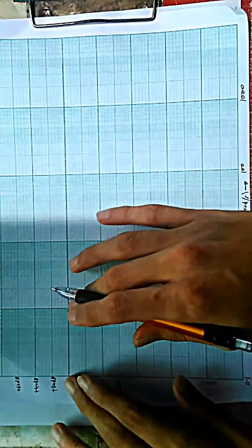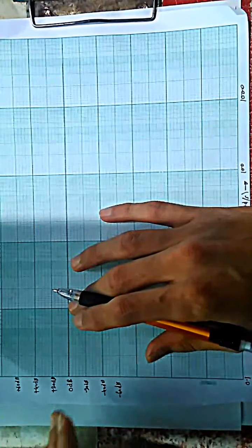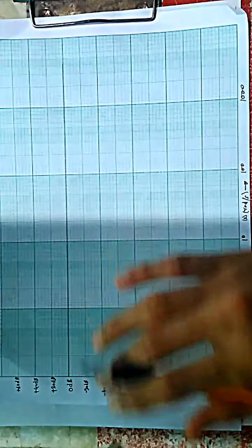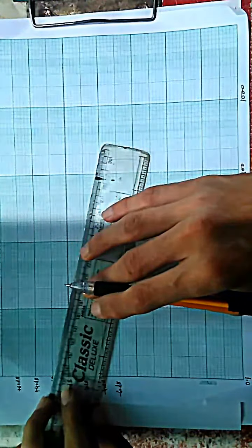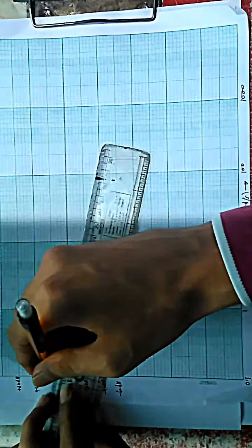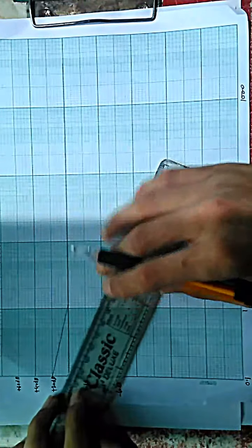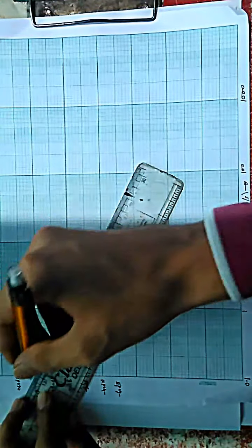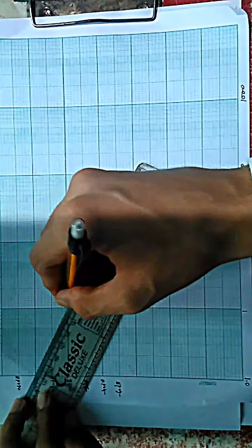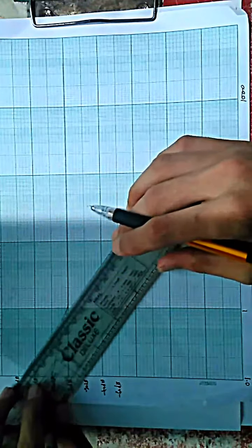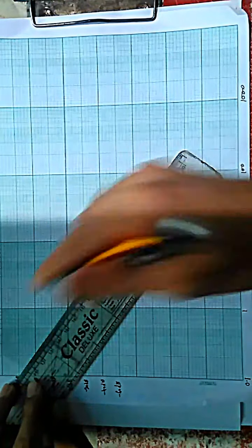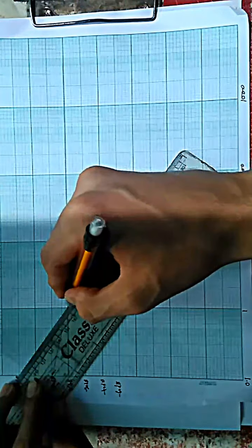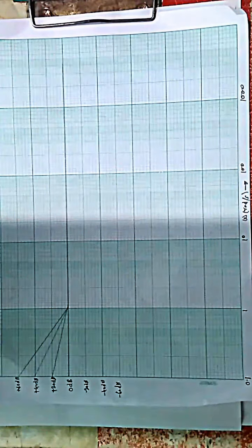This means in 1 decade, the slope falls from 20 dB to 0. Similarly, for minus 40 dB per decade, the slope falls from 40 dB to 0 in 1 decade. Similarly for minus 60 dB per decade. These aren't part of our Bode plot, these are just for our reference.